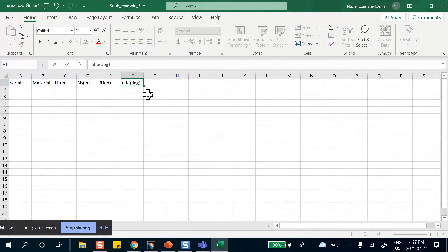Now, please make sure you're with me on this: you put these only for safety reasons, because your database units may be millimeter and radians, and if you don't put these things here, you just put numbers, it's going to use millimeters and whatever radian. But my units are inches and degrees, so I don't have to put these things in there. But for safety reasons, make sure you don't lose any marks. If there is a mistake, put it there.